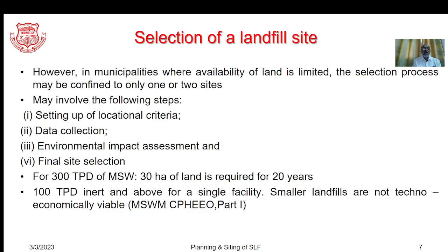Here one must take into account a certain thumb rule. Say for example, for 300 tons per day, 30 hectares of land is required for a design life of 20 years. One must not go for a capacity lesser than 100 tons per day because it would be a costly affair and it won't be a techno-economically viable project.